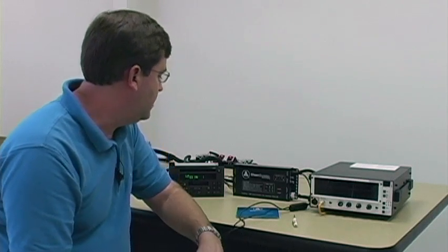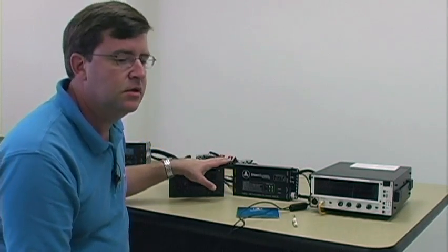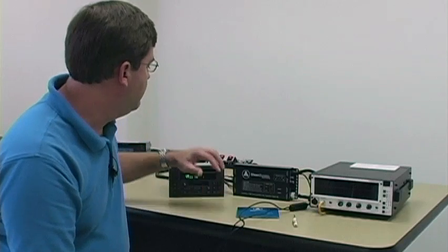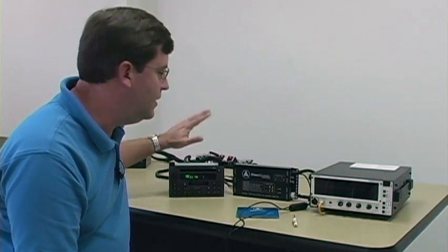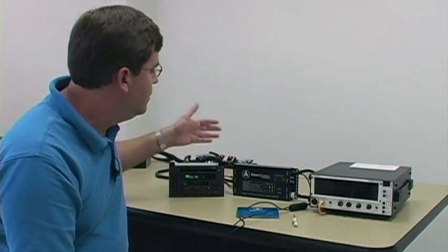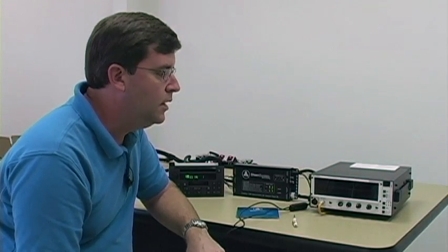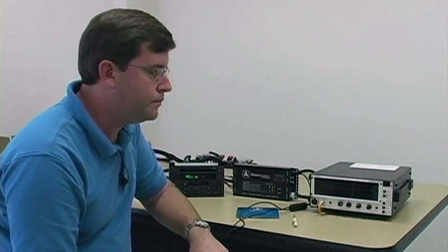Okay, we're going to look at an application here with a radio out of a Lincoln, and this radio and audio system in this car is actually very common in most of the Ford premium systems. Let's say we didn't know much about it when we started, and we simply grabbed the 4 head unit outputs that come out of this radio because they were easy to find and obvious front and rear speakers. We plug them into the front and rear inputs of our CleanSweep DSP processor, and we attempt a calibration.